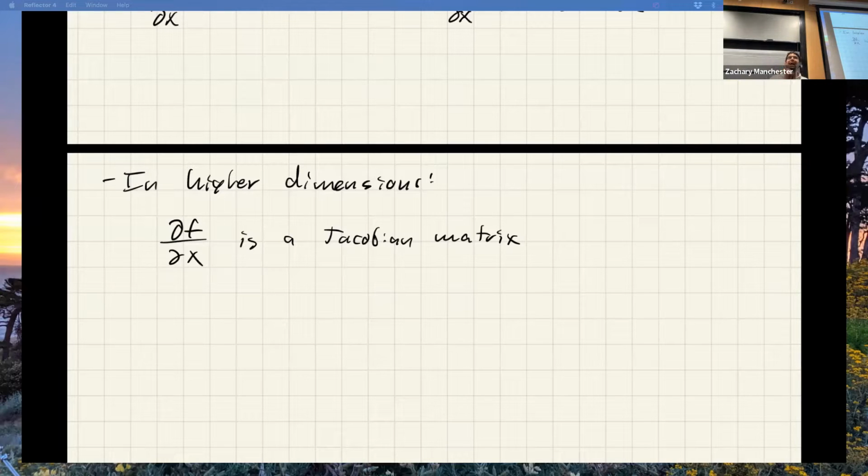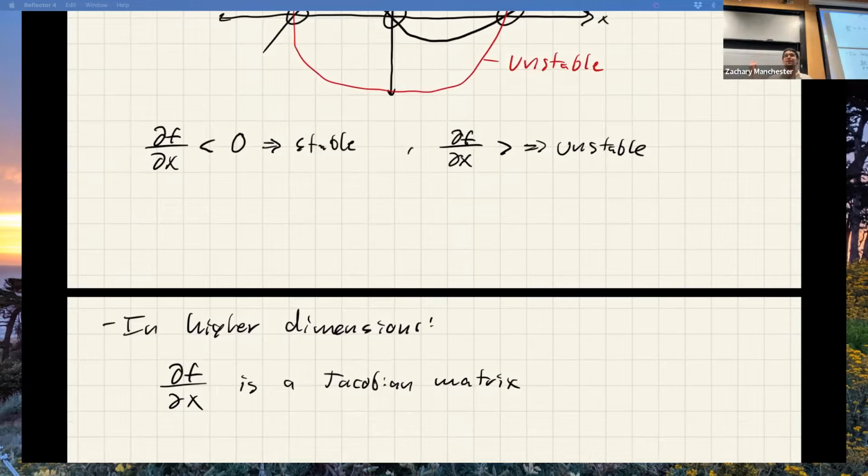So what we're going to do here is take an eigen decomposition of this guy, which does what? It finds a coordinate transformation, the eigenvectors, right? An eigenbasis such that this matrix is now diagonal, which means in that particular coordinate frame or basis, you've decoupled the dynamics into a whole bunch of 1D systems. So now I can use the simple 1D result. And basically all of these conditions just get applied to the eigenvalues now, right? Which are all the decoupled 1D systems. Make sense? You got that? So that's it.